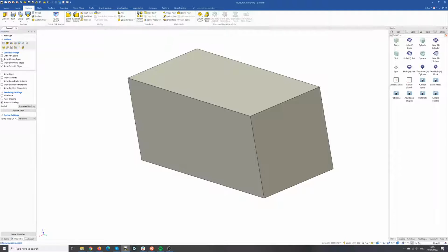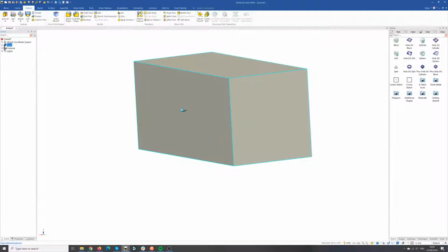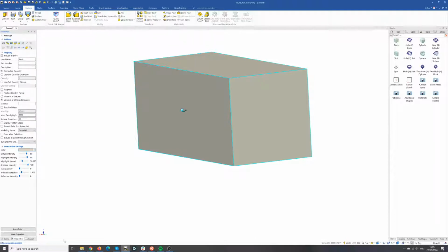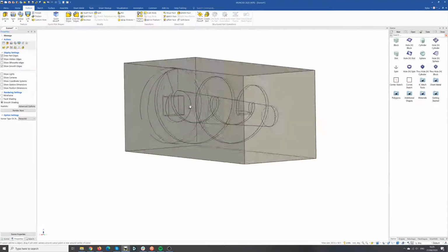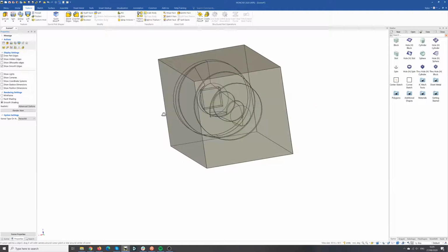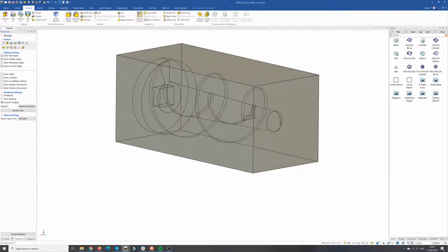And if you then show the hidden edges, you can actually now see, if I can now select it. Okay, let me go to properties here. You can see I've only got the one part there, but if I go back to properties, I can then show, oh, turn that off, show hidden edges. There we go. It just got its knickers in a twist, and there I've got that part already as a subtraction. If I was to open it up and do a split face and just move it all the way across, that will show you what's inside.